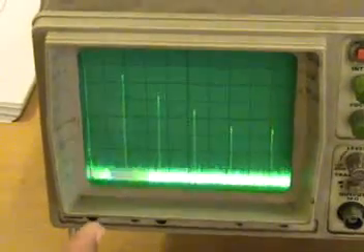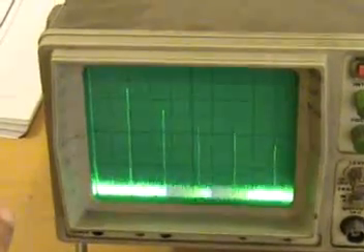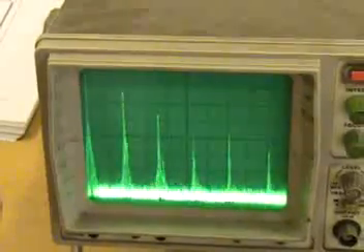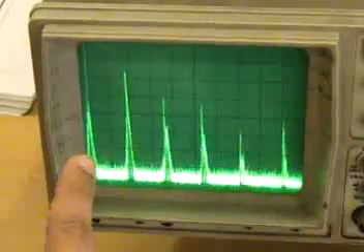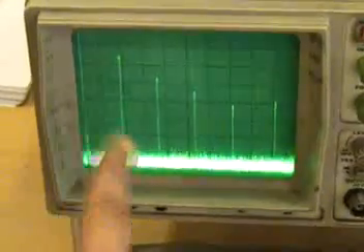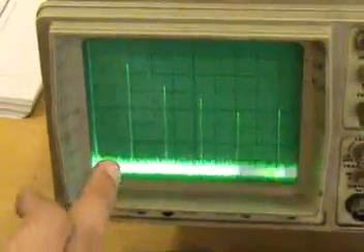If we again increase the voltage, the oscillator comes back into its overtone mode. It tries to push to cross the resonant frequency of the crystal, and now it locks into the center frequency of the crystal, and we have a stable output of the Butler crystal oscillator.